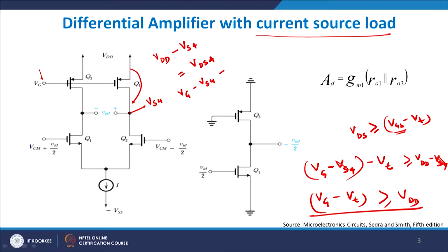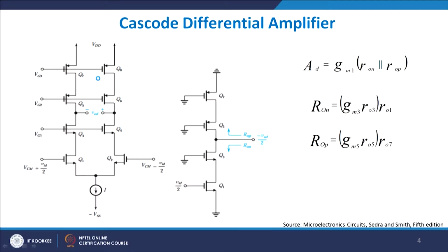So, once you are able to sustain a large value of Vg, say if your Vdd is 2 volts and the threshold voltage of these devices is 0.7, then you have to give at least 2.7 volts at the gate side to make them behave as on-state devices, and they will act as resistors here, right. So, these are active load devices which are there with us.